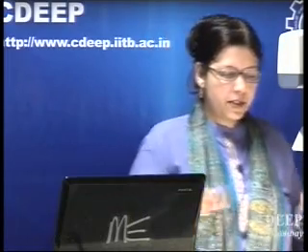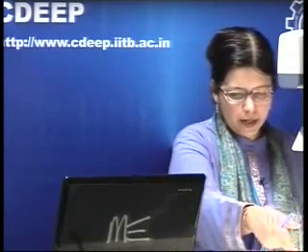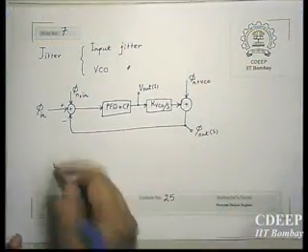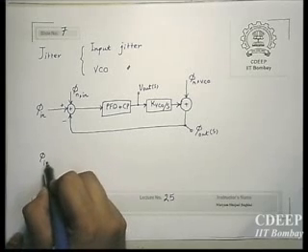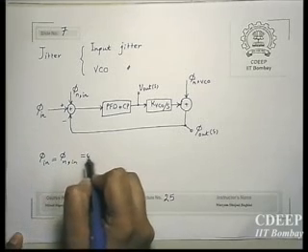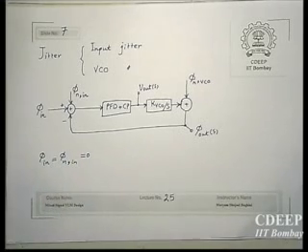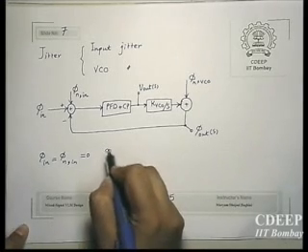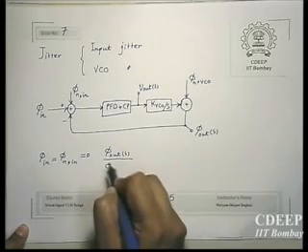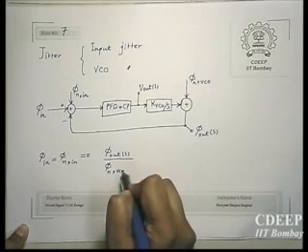But if it is at the phase noise side, that is the VCO side, then now your input is here. Therefore, to get the transfer function, you make phi in equal to phi n in equal to 0, and then get the transfer function with respect to phase noise of the VCO. Therefore, phi out with respect to phi n VCO.